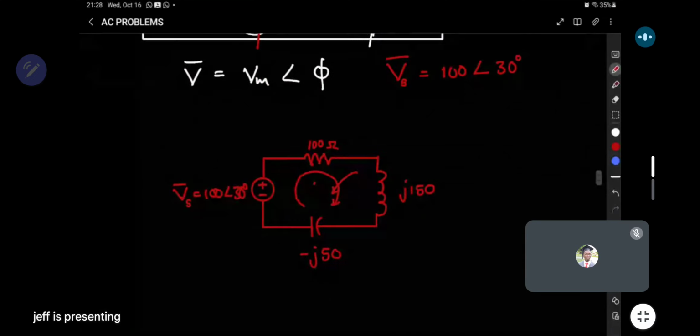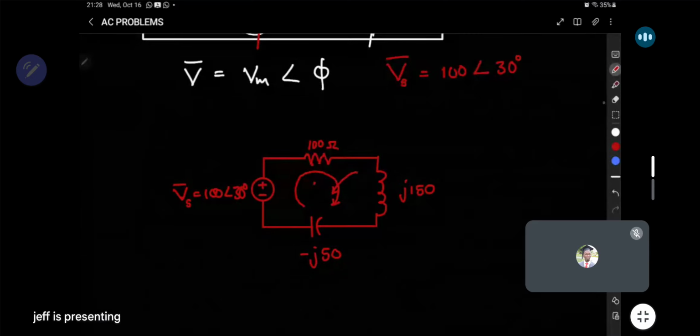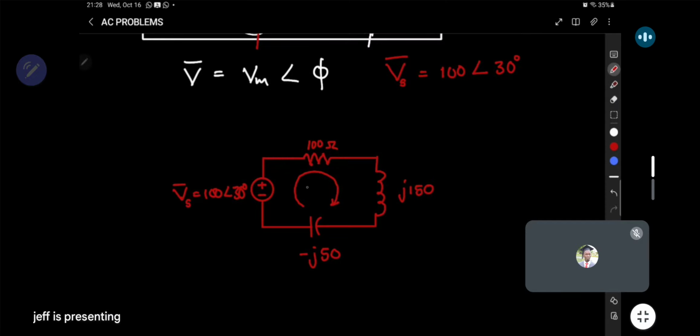Okay, so with that answered, we were somewhere here. For this expression, once we have changed it to this format, the current that we are now seeing is no longer the time dependent one. It's no longer the sinusoidal waveform. This is now going to be the phasor current. Now, once you have made the transformation, everything that follows is the same as what we did in DC circuit analysis. So the same rules will apply: mesh analysis, nodal analysis, Thevenin, Kirchhoff's, everything is going to play a part.